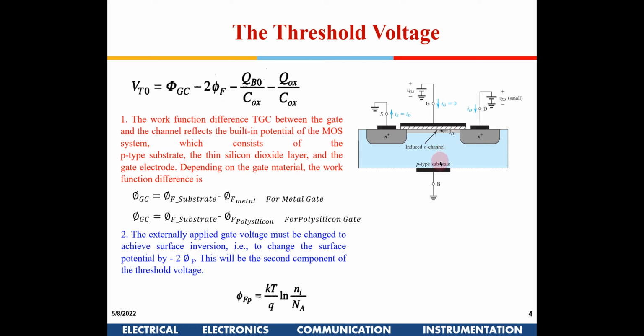We are doing constant voltage scaling, that is, we are shrinking the device size, but we are also going to reduce the VDD by the same factor, so that the electric fields are kept constant. If you don't keep the electric field constant, and you just reduce the size of the device, then there is a possibility that high electric fields will be set up, and that will damage the device, right?